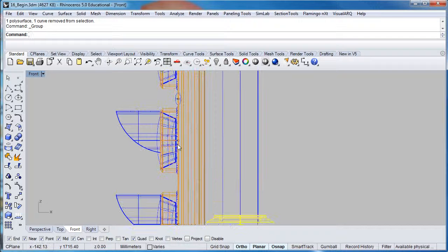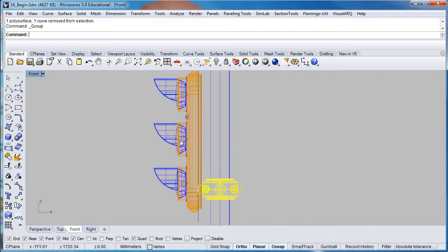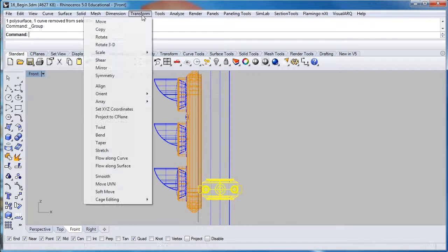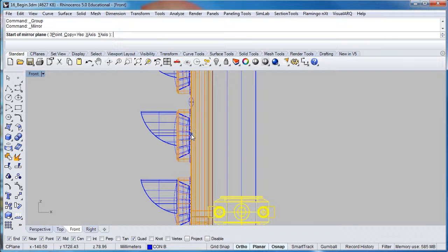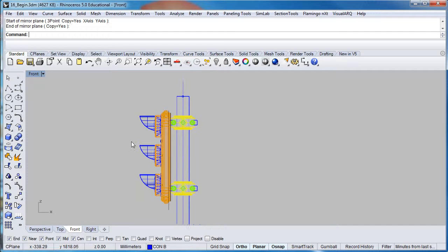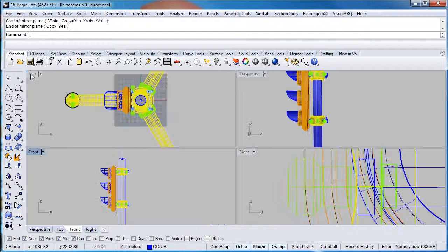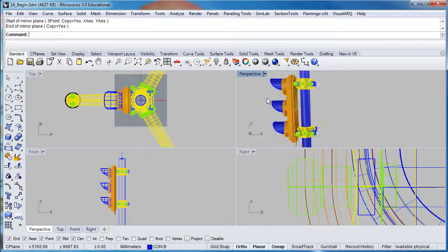So in order to do that, we have this spot just here, or we can use the midpoint, but we're going to use the transform command, scroll down to mirror, and keep your snaps on. Take off quad, and we want point. There's center and point, and if we scroll out, you can see it's now mirrored to the top edge of that element, and everything's in position. Double click on front, and you can see we have both mounting rings in position now.